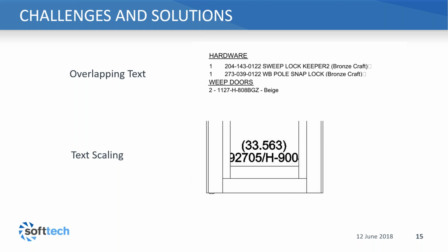I would place the text for the weep doors header, and the underline here is actually just an AutoCAD line that was added. Then we run what we call a selection set using a crossing polygon, for the AutoCAD people here, and we determine how many entities ended up in that selection set. In this case, we should only have 2. If there's more than 2 items in the selection set, then we obviously were overlapping something. We've put our weep doors on top of another item.